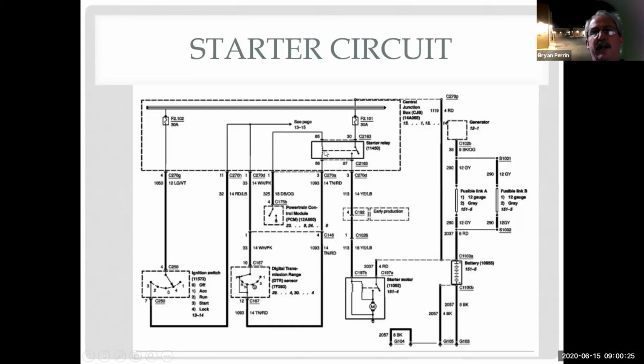But what else do I need? I need power and I need more than just power, don't I? What do I need? I need positive and ground. So the ground has to go to the other side of the relay.